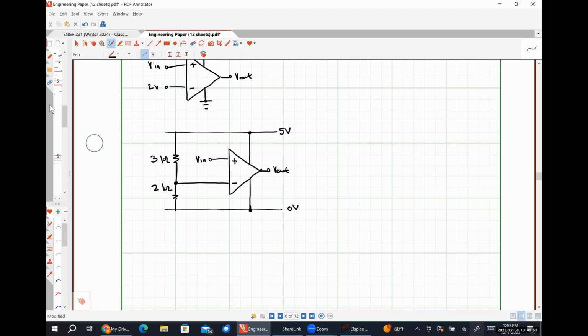All right. So the answer is for which part? From one, it's just graphics. Yeah. Like 18. So the peak value of the input voltage is 1.5 volts, right? Because that says 1.5 and that's the maximum. I'm trying to figure out whether or not saturation distortion will be a thing. So if it's below the peak value, that's less likely to cause it to saturate. Same thing for the negative. Yeah, exactly right. So my voltage gain is defined to be 12. AV is equal to 12.